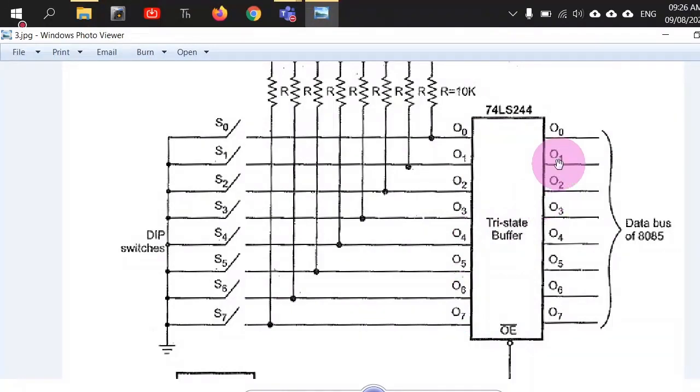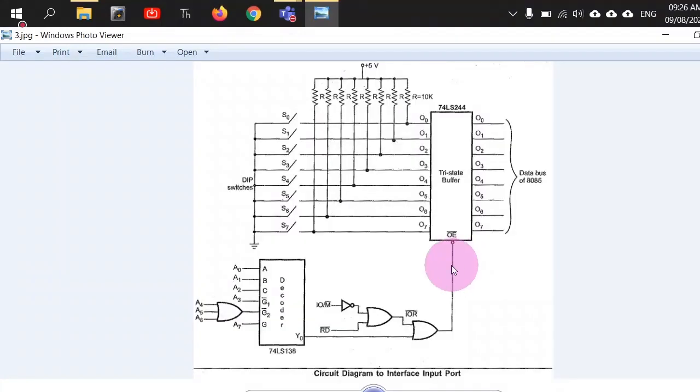So I will relate it to the IO mapped input output. First of all, just understand the circuitry, right? So now if you see, we need to have a 0 value here. And for that purpose, this is an external device which you have connected to your microprocessor's data bus, and you are supposed to read some data from this externally interfaced device. And here you are treating this as an input device because it is giving you some data. Now, as I told you, this IC will only be activated when this chip is activated. So this chip will be activated when this signal is 0.